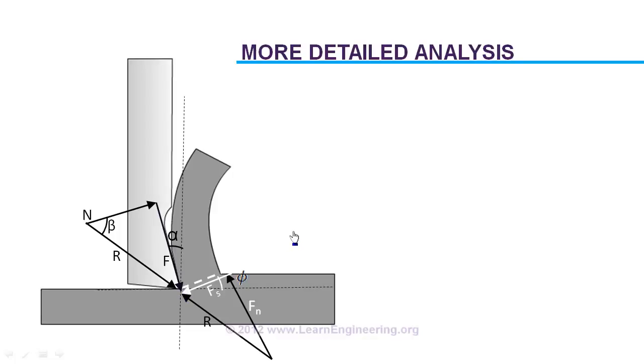For that we will start from this resultant force side. For this force, obviously you don't know the magnitude, but you know the direction. You can prove that this is an angle alpha minus beta. So you draw a line at an angle alpha minus beta with the horizontal, and on this line we will attach the shear force. The magnitude of the shear force can be determined in terms of shear strain rate and properties of the material, and you already know the angle of the shear force, so you will draw a line with magnitude Fs and angle phi with the horizontal. It will be like this.